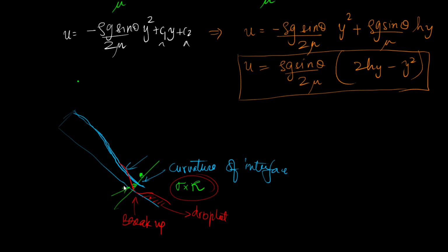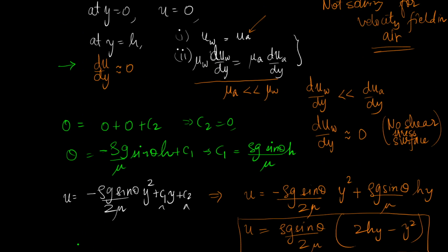So yes, we have made a lot of assumptions behind this particular problem, and each assumption has a different ramification on the simplification of the problem: the flatness of the interface, fully developed flow, and all this. Each assumption does affect the solution methodology, and this particular velocity profile is at best what is known as a leading order velocity. One small assumption that we have overlooked is this.